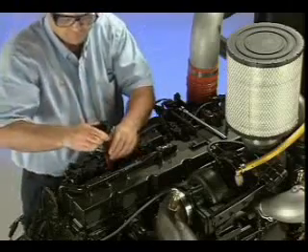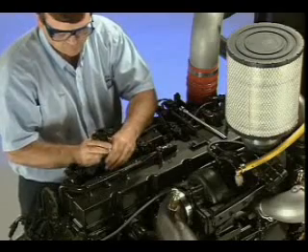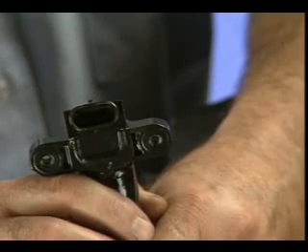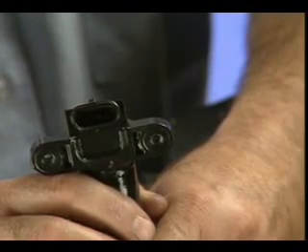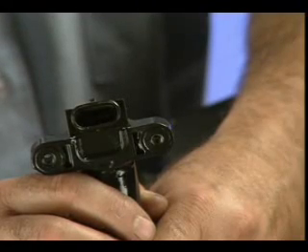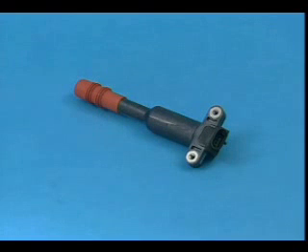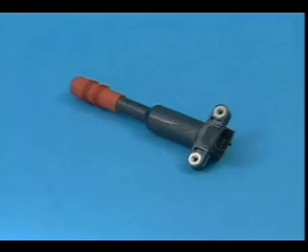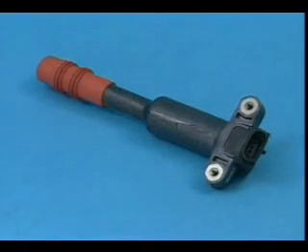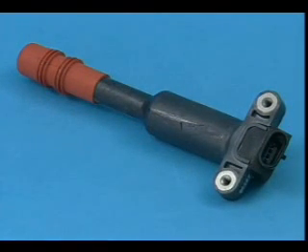The coil-on-plug has a grounded mounting pad for secondary wiring return. The mounting pad is on the right side when the opening for the wiring harness connector is facing you. Inside the coil housing, this grounded pad is connected to the ignition control module return line. This wire is the return for the coil driver. Most of the current flow through the secondary windings goes through the ground in the mounting pad. This isolates it from the ICM circuitry and improves the noise immunity of the ignition system.